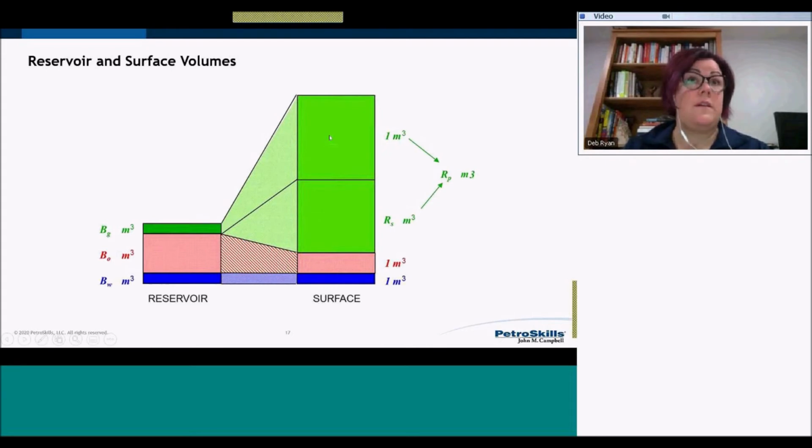And it's one of the reasons when we're looking at production data, we have to be really careful that if we're using production data to characterize our fluids, we make sure we do it at the beginning of production, before we have free gas in the system. In order to characterize what that dissolved GOR looks like at the beginning, so that we can understand how this fluid's going to behave, we need to make sure it's before we've dropped below bubble point, after which the gas oil ratio is increasing because of all the free gas.